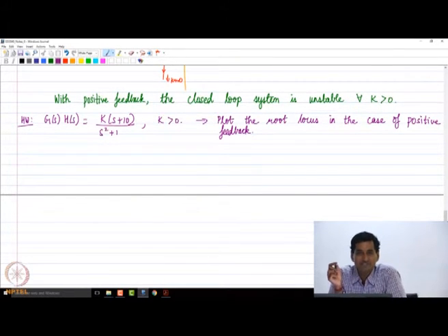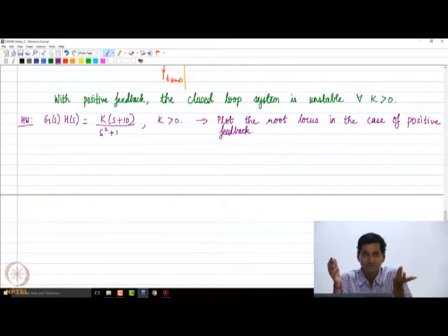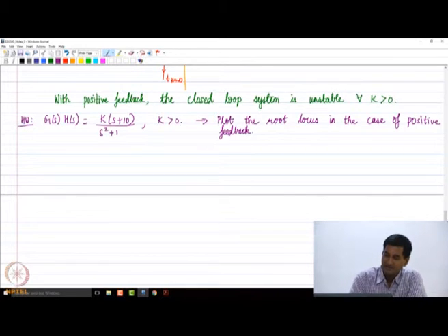Now we will come to our friend's point. What happens when k is negative? So till now I have been sticking to a case where k is positive, but it need not be, because let's say k is a controller gain, like in the example that we did last class with the vibrating system. Let's say k we pulled out of the proportional derivative controller, and basically it was a controller gain. So now the question is, it's a real number, so it can have both positive and negative values, but till now we have only plotted the root locus for positive values of the parameter k. What happens when you have negative values? That's something which we are going to ask ourselves now.